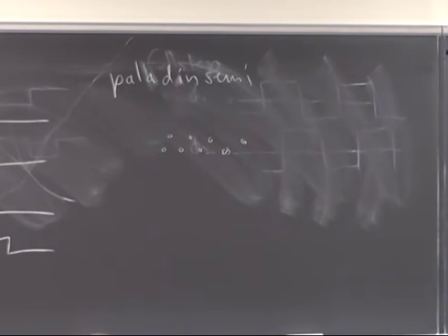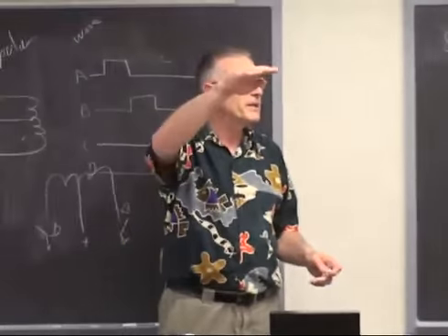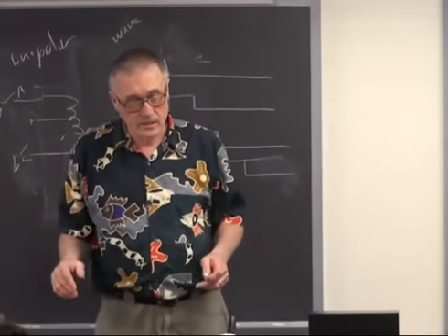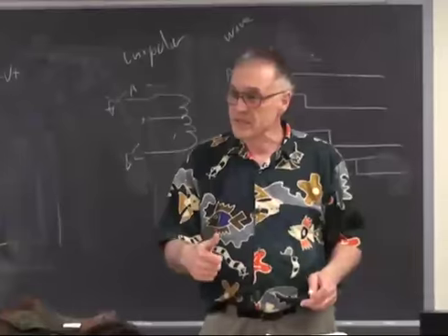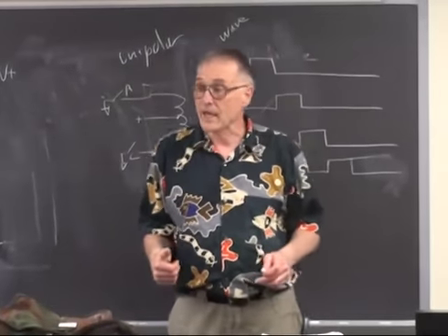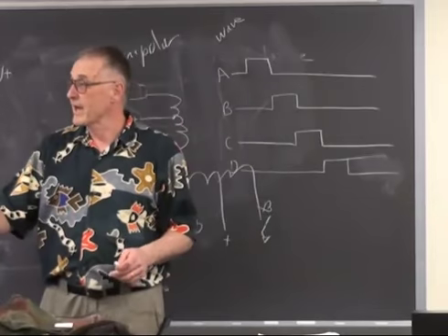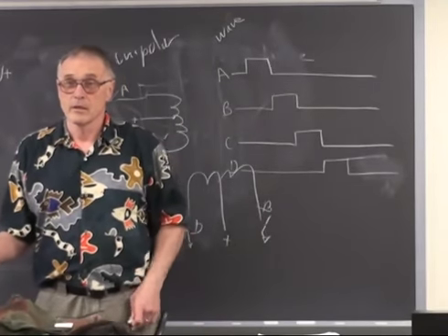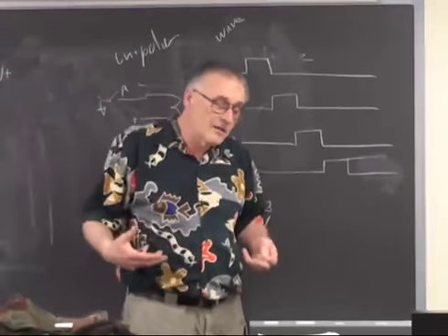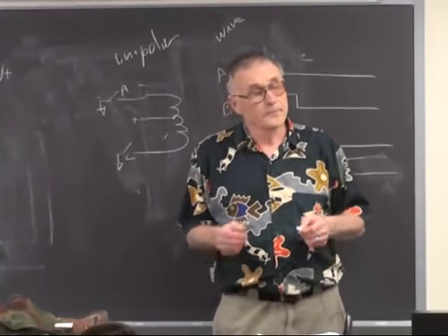And you can do things like give it commands to ramp up in speed, using some of the stuff from Paladin Semi. Ramp up in speed, ramp down in speed, single step, set the step rate, set the number of counts. So go forward 35 counts and stop. So there's lots of high-level solutions to this.